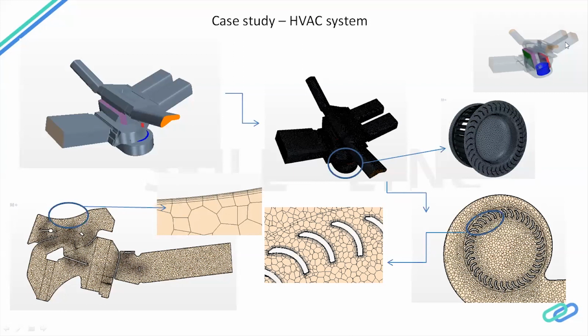So this HVAC unit is about heating, ventilation, air conditioning. Heating is about heating of the fluid. This red box is the heater. Ventilating means purification of the ambient air. Before this segment, you have some purification where the dust particles are removed. And air conditioning means we cool down the air to produce the cooling effect for the passengers inside the car.